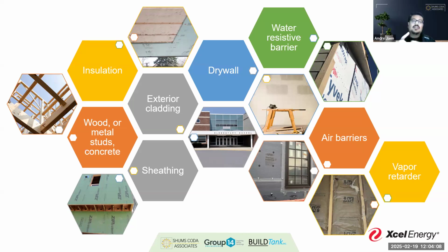We have our drywall or our interior plasters and finishes and things like that. Those are necessary components to building those walls, and those inform us about what's going to be behind it, how it's going to be used effectively, where that air barrier is going to be again. We also have water resistive barriers. Here we have kind of the classic representative of the residential industry. It's usually referred to by name at this point as Tyvek wrap. Now we know that water resistive barriers can be a number of different products that we'll look at today. Things like 15-pound felt, which was used for a good long time. A number of other products out there, and then some assemblies also meet that requirement of water resistive barrier, right? So we're going to look at where all these different requirements come from.